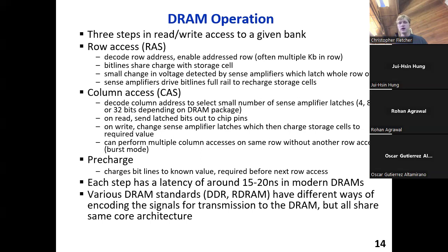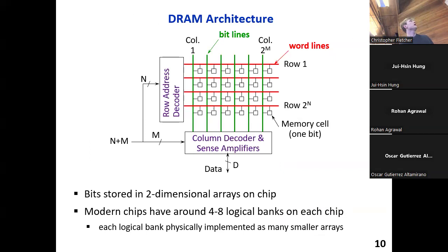That's exactly right. So going back to our picture, there's no sense in sending the column address first, because the column address is like a select signal into a multiplexer. There's no reason to send that select signal before we have the inputs to the multiplexer ready. The inputs are all of the bit lines coming down.